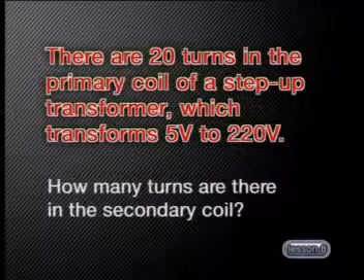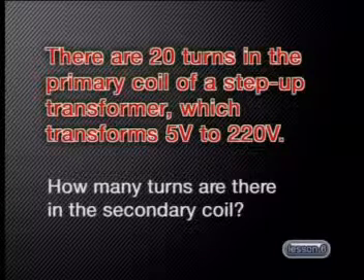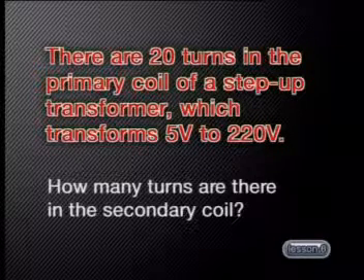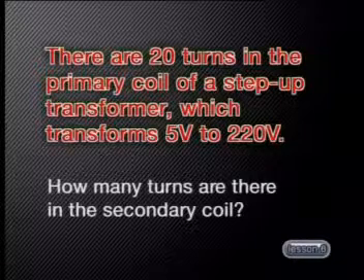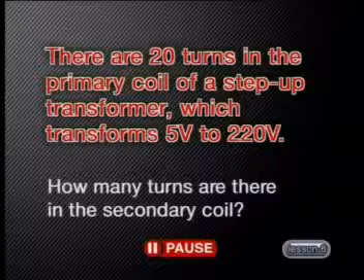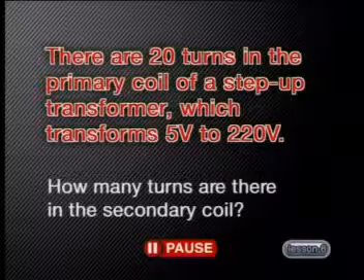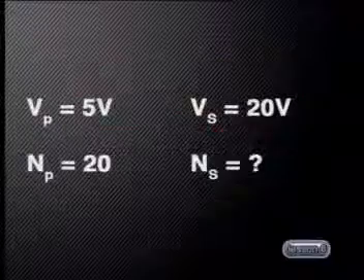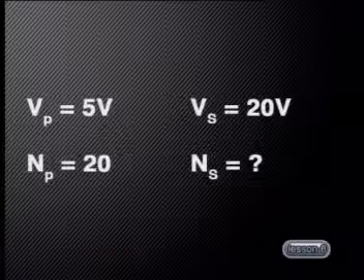Have a look at this example and see if you can solve it. There are 20 turns in the primary coil of a step-up transformer, which transforms 5 volts to 220 volts. How many turns are there in the secondary coil? Compare your answer to mine.